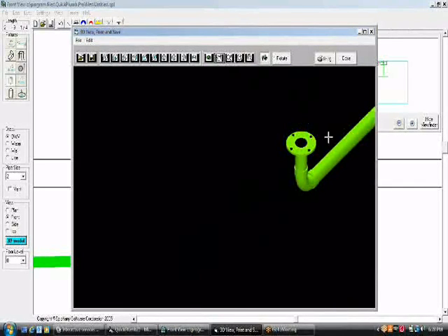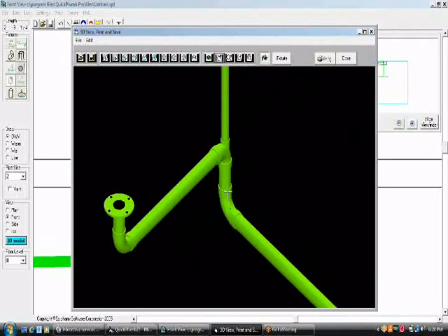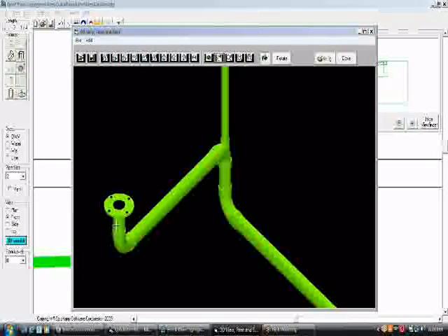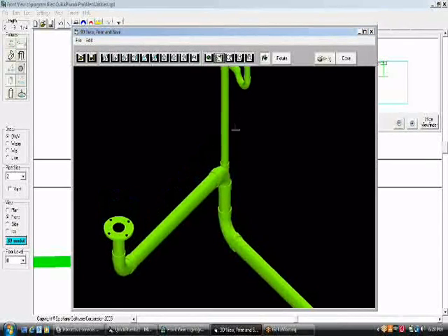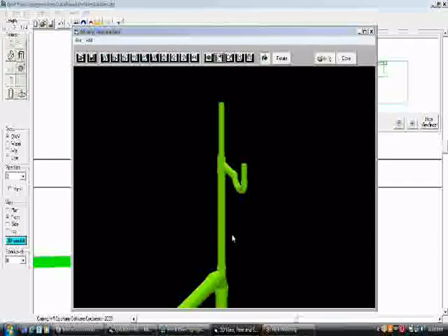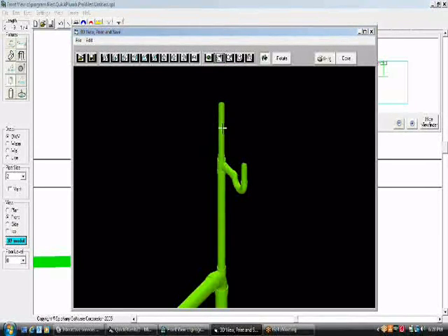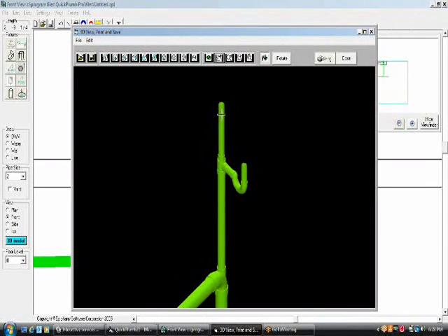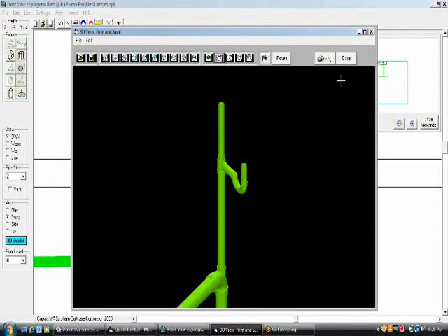the fittings that were added were a sweep at the base of the stack and a heel outlet quarter bend here, picking up the water closet, and then the vertical wet vent continuing up to the lavatory drain, and then our vent here that will be either Studor vented or continued out to the rest of the venting system and through to the roof.